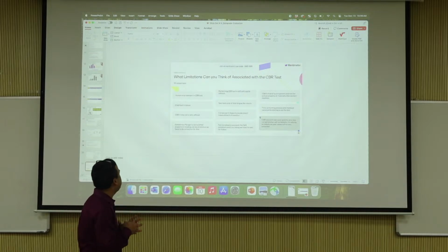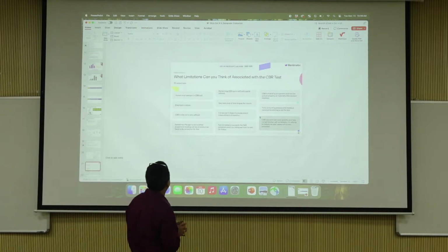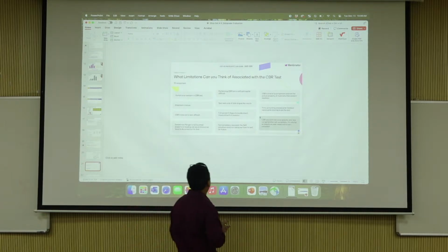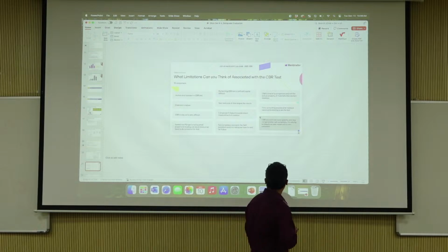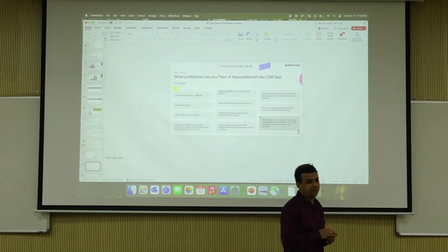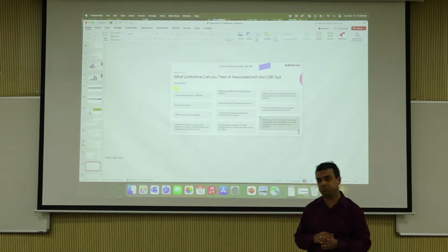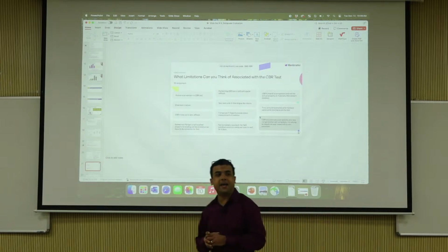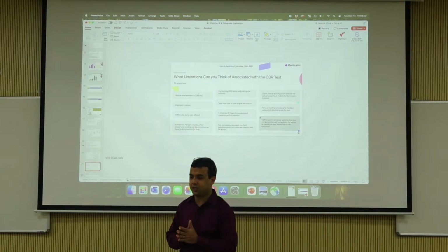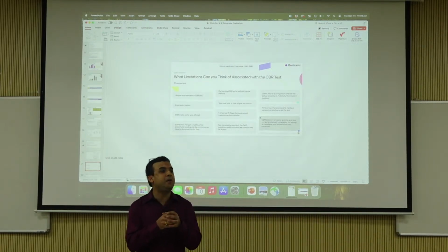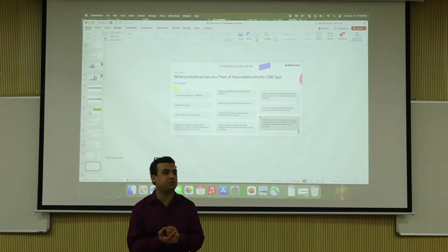I see some of them are practical concerns you all have, like for example, human error. The test takes a lot of time. It's difficult to run on clay soil and stuff like that. True. Okay, but I actually have a different question. So you have a steel plunger that is going into the soil, right? When was the last time you saw a steel plunger going into an actual pavement?